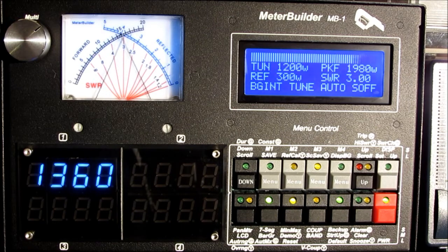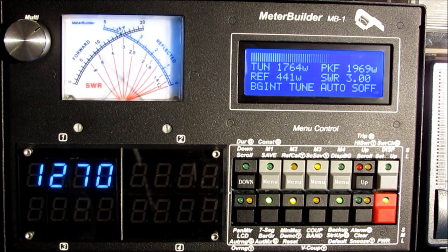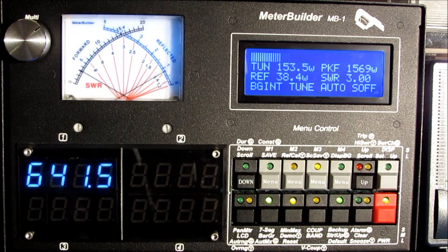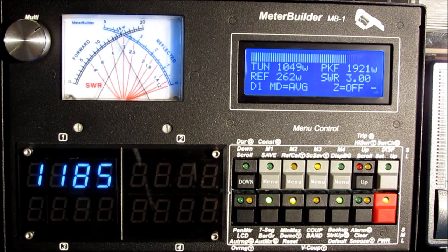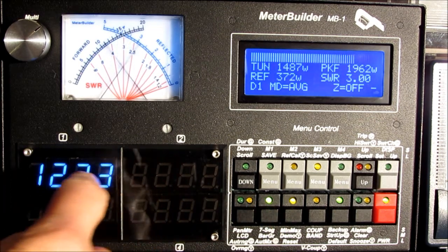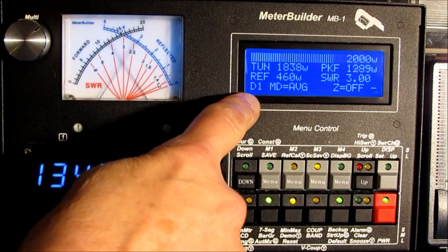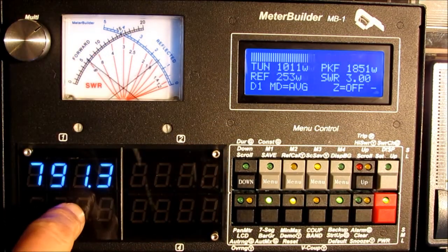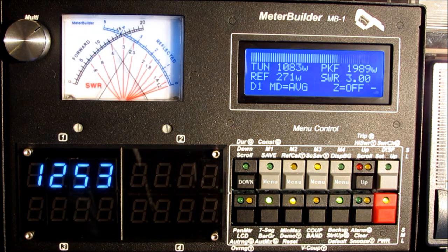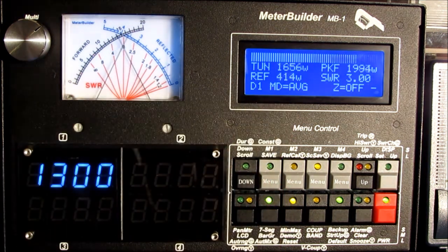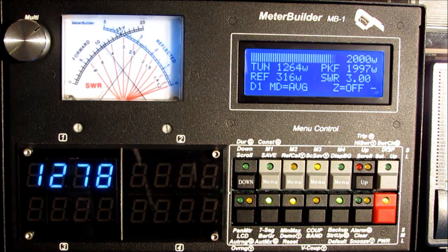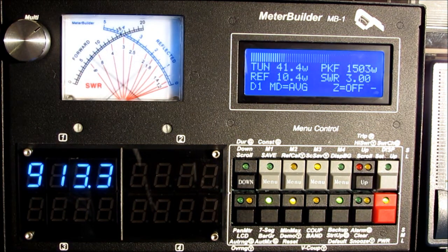Let's use the 7-segment setup as an example. Right now I'm showing the bar graph menu. A single push of that shortcut button will bring me to the 7-segment display menu. The first field selects which of 4 different LED modules I want to modify. The second field selects the mode or measure parameter that I want displayed on that particular module.